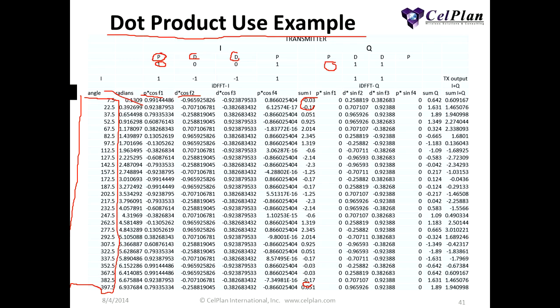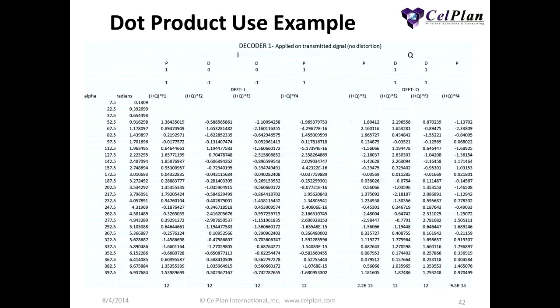Here I didn't put any parity. And then when I join this together, I can sum I and Q, and this is basically the waveform that is transmitted. This is very interesting because this was done in Excel, and the same thing happens when we generate an OFDM signal. There is no analog manipulation of sine waves and so on. Everything is done by using numbers, because these analog sine waves are digitized. So each sample has a number associated to it, and what we are doing is processing numbers. That's what makes OFDM very attractive, very efficient.